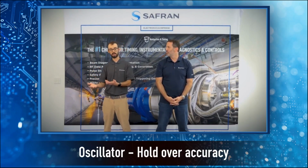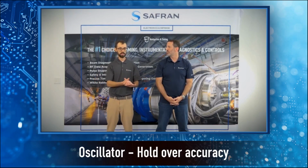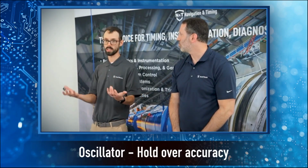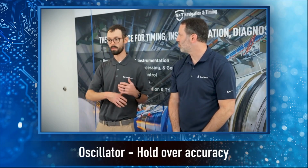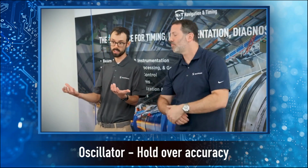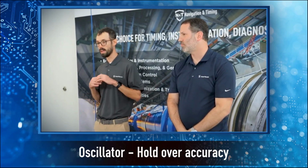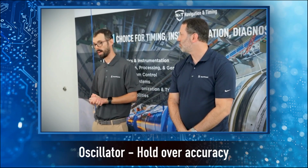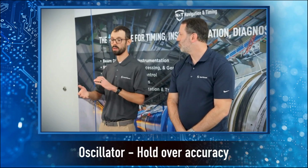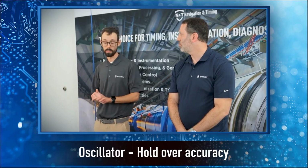That's usually where we'll look at the rubidium. We don't typically talk a lot about TCXOs, but we do still offer those for applications that are cost sensitive. So much like Dave was talking about with the chassis types, the 2 versus 6 being a cost savings, the TCXO would also be a cost savings. Our standard unit that we provide is an OCXO unit. It gives you decent holdover and accuracy for the money at that point.